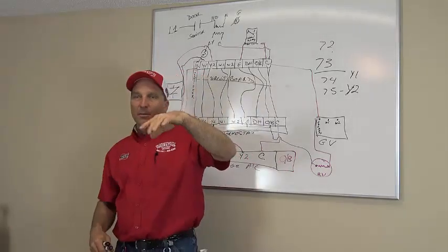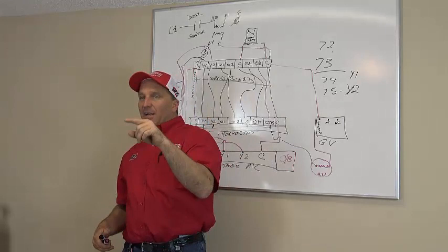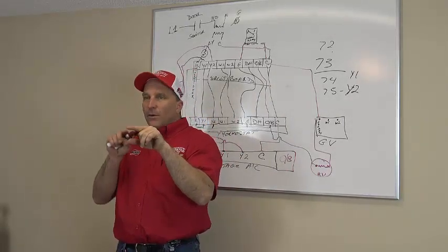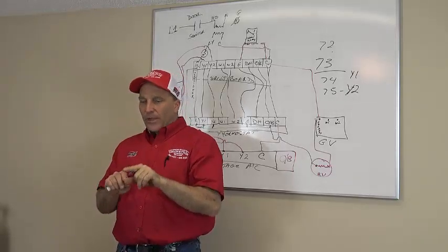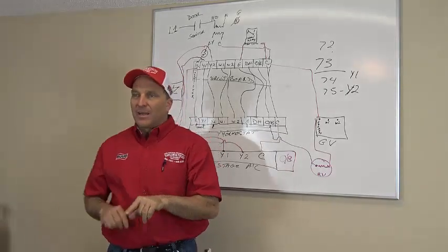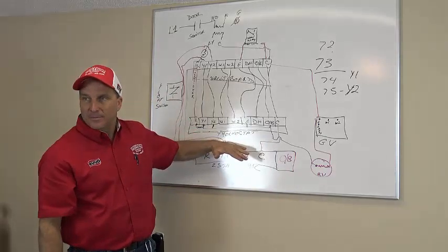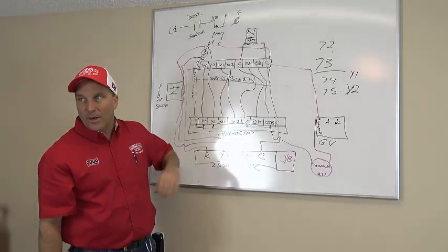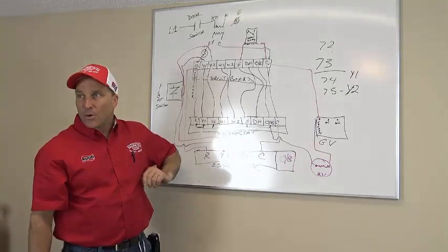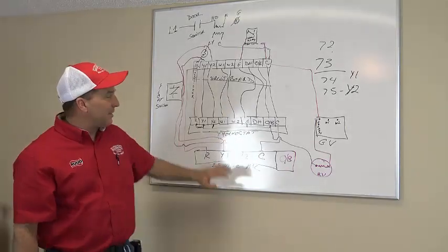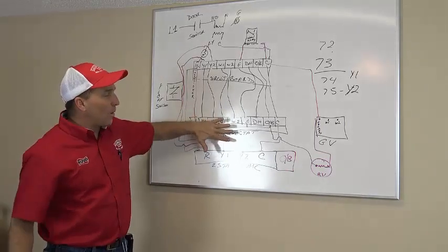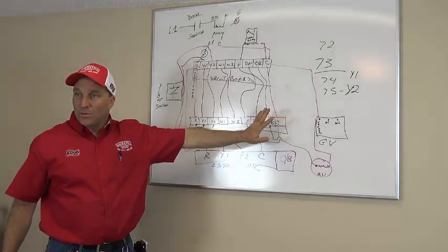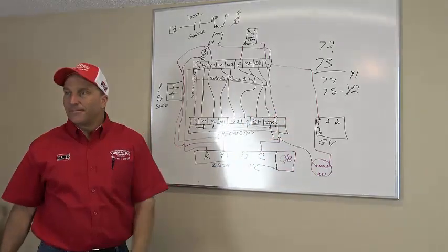And when you get to number, I'm making this up, when you get to number 10, it says, okay, which thermostat do you want me to be? 1, 2, 3, 4, 5, 6, 7, 8, 9, 10. Okay, I want you to be number 8 because number 8 is a two-stage heat pump. Okay? Two-stage heat pump, dual fuel, right? That's what we got here. So if I'm two-stage, that means it knows I got a Y1 and a Y2 and it knows I got W1 and W2 too.